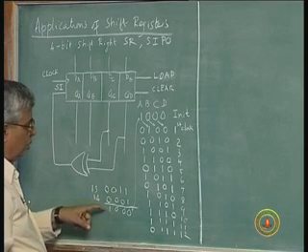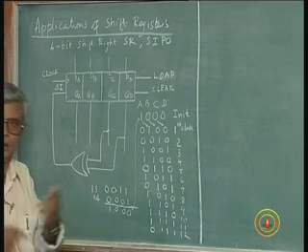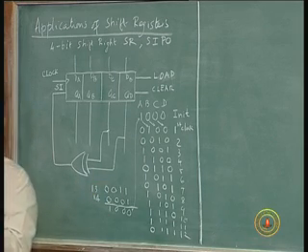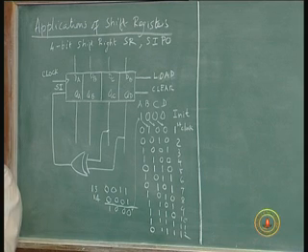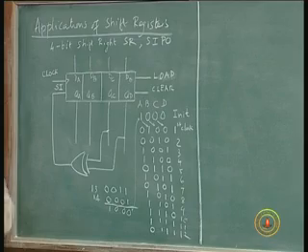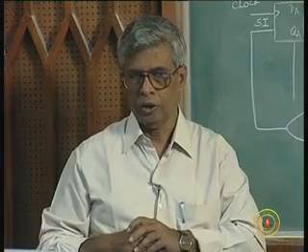So this is 0. So 15 clock pulses. After 15, so the frequency of repetition is 15 clock pulses, 15 clock durations. After 15 clock pulses, the original pattern is restored.